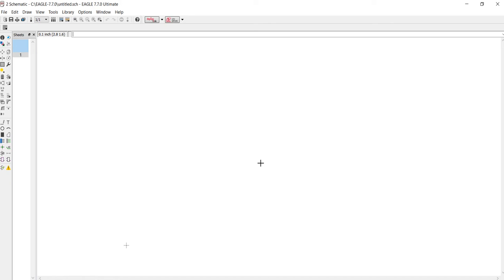That's all through, another word for that is through hole, so you'll be able to hand solder this very, very easily if you do decide to fabricate it. There's really no difference if you wanted to do this as a surface mount component, and in the library you should be able to find all the parts in surface mount as well if you decided to do that.